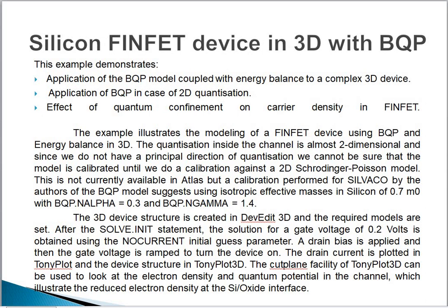Next is the code we will discuss in the next slide. Silicon FinFET device in 3 dimensions with the BQP model. This example demonstrates the application of the BQP model coupled with energy balance to a complex 3D device. Application of BQP in the case of 2D quantization. The structure looks like 3D, but the quantization is actually in 2D mode. The effect of quantum confinement on carrier density in FinFET we will discuss.